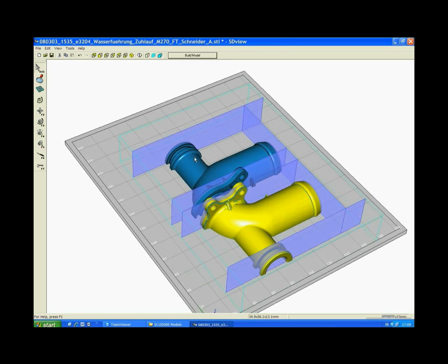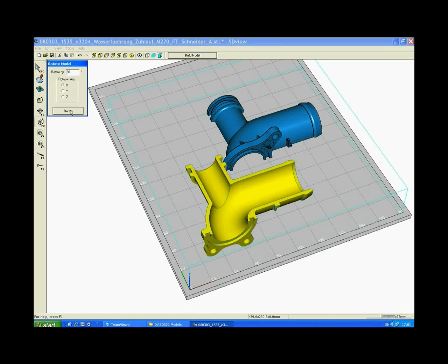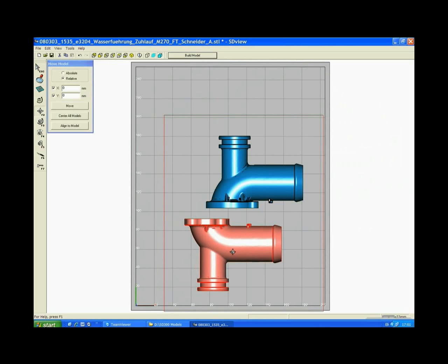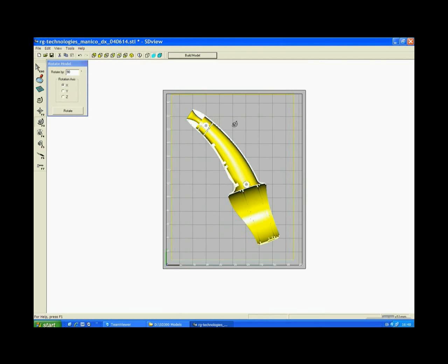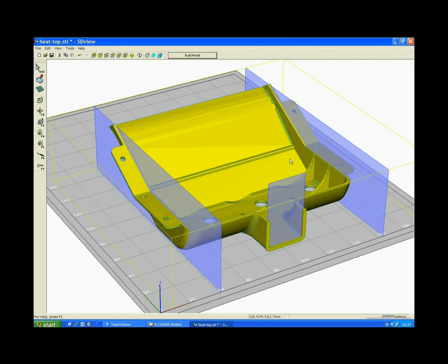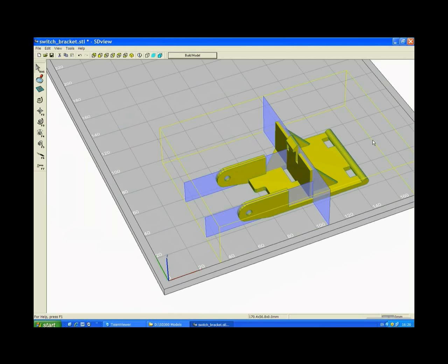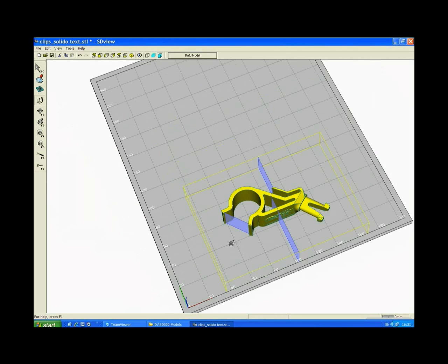Peeling cuts should be placed as the last feature when preparing the model. The model should first be rotated, moved, scaled, and so forth before placing the peeling cuts. Place the minimum amount of peeling cuts required to get the maximum peeling effect. Too many peeling cuts will take additional time for the model to be built and are not always necessary.